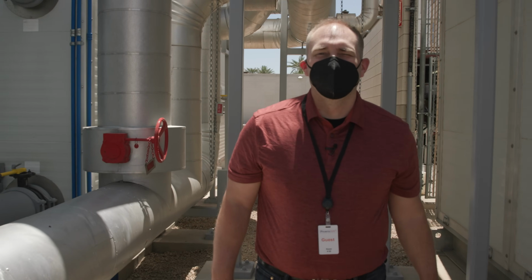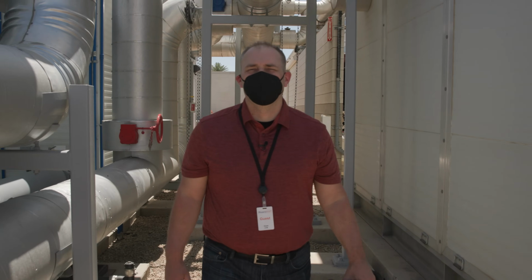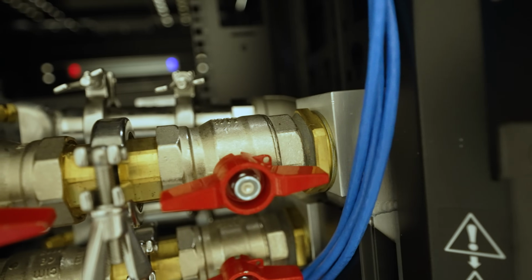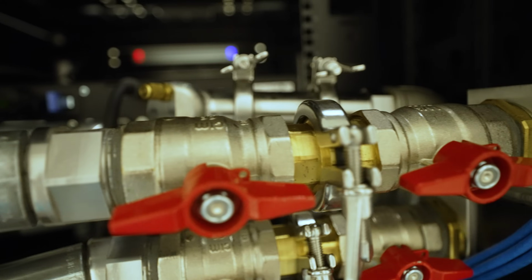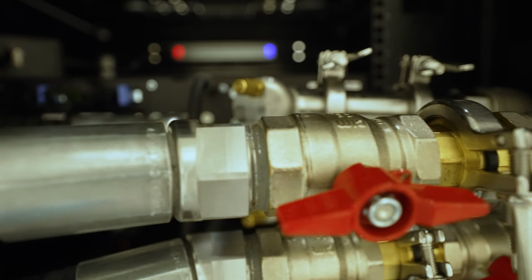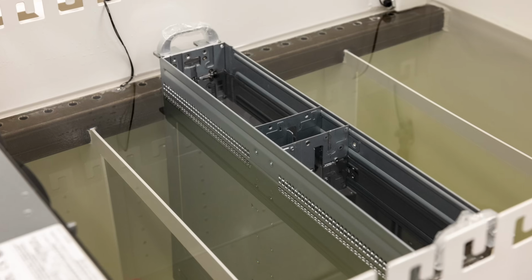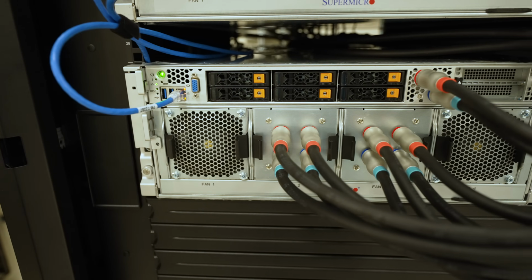This next generation, and really if you want to get into that 40 kilowatts and higher per rack level, you're most likely going to have to bring liquid into the rack to be able to handle that kind of heat. So with that, let's get into some of the solutions that you might want to deploy. I'm just going to show you what's out there, really talking about the basics of the rear door heat exchanger, immersion cooling, and then direct to chip liquid cooling.